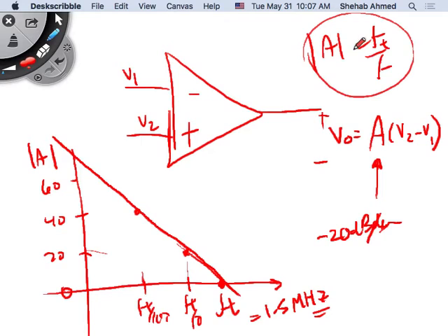I plot this, which is an approximation of the op-amp's transfer function, which they gave us as Ft over F. What does this look like? Ft over F, plotted on a log scale, looks like a straight line. And they're telling you that A0 is a characteristic of the op-amp, but we don't know exactly what it is, and in manufacturing you cannot tweak it.